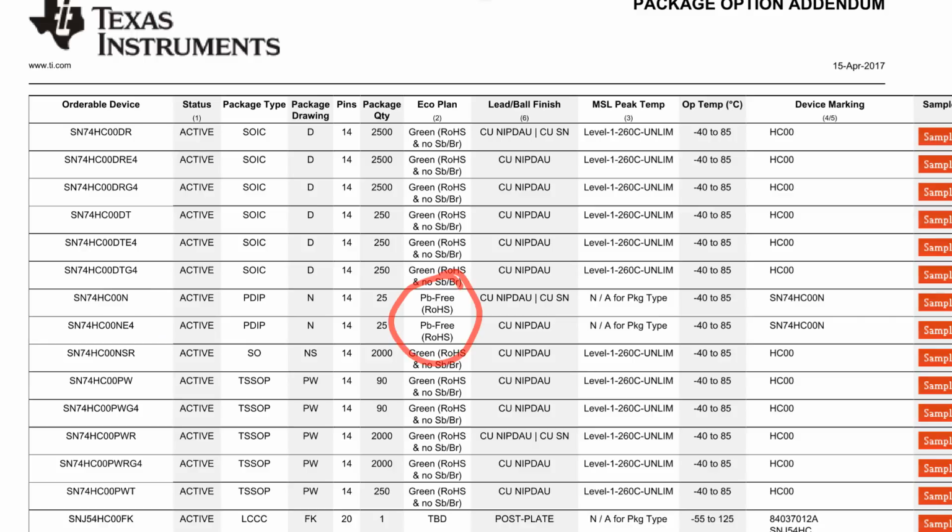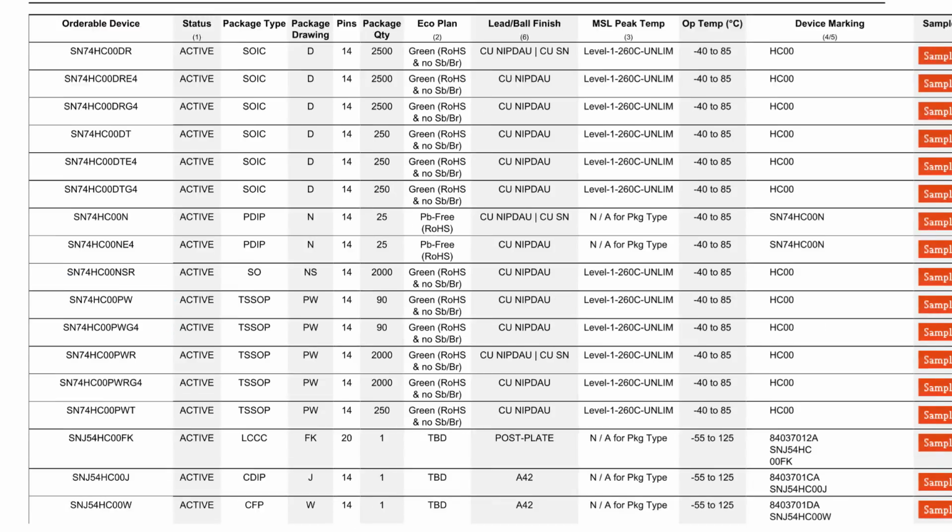Both are lead-free. Aha! One of them has a different finish on the pins. There you go. So if that mattered to you for RoHS compliance, they're both RoHS compliant, so they're both lead free. But if it mattered to you from a soldering perspective, if you're designing a probe flying to Pluto, you've got one shot at this, you're going to have a dedicated engineer in the group looking at the soldering and the metallurgy and all that sort of stuff. So if your purchasing department ordered one instead of the other, that could ruin your space probe.